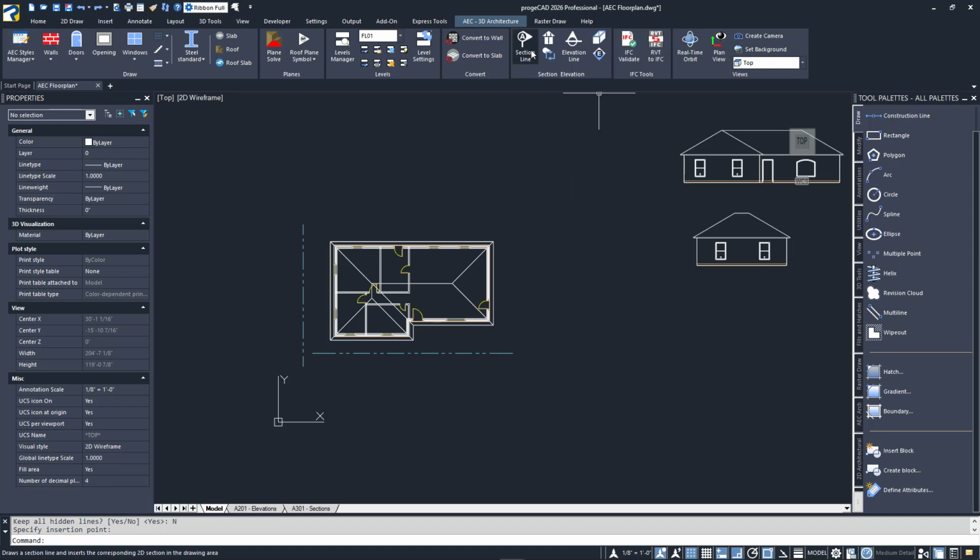I'll click on the Section View tool, and again, I'm prompted to draw the line. Remembering my lesson from the last elevation, I want to make sure the direction I want is the section to view. Notice this time, instead of ending at the second point, I can choose to continue. We'll do that next, but for this one, I'm done. I'll follow the same workflow to place my new section view.